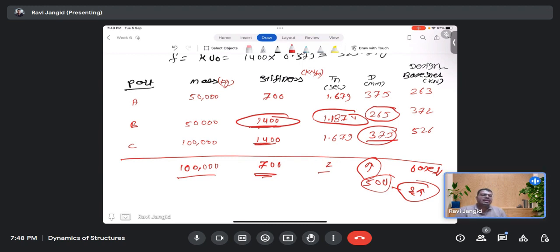You cannot say that if I increase the mass, then at the same time you need to look into the stiffness also. What is happening with your stiffness, you also look into this. Can we optimize this, like base shear? The main thing for a design is that we have to have less demand, right? Yes, less demand. For that, can we optimize mass and K?